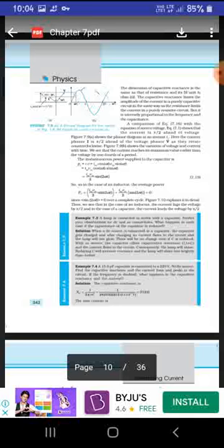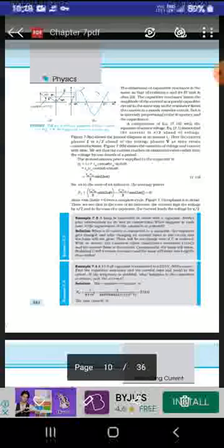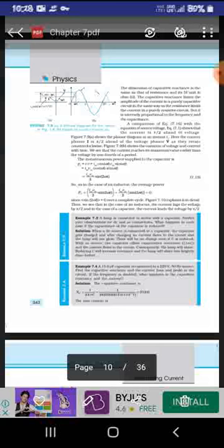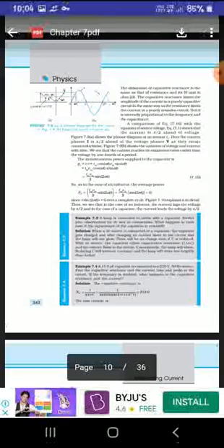Here they have given a phase of π/2. The voltage phasor V rotates counterclockwise, as you can see in the diagram. As it rotates with time, we see that the current reaches its maximum value earlier than the voltage by one fourth of a period. So it reaches it faster, by one fourth of a period, than the voltage.